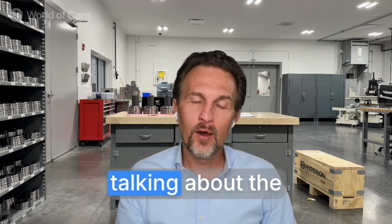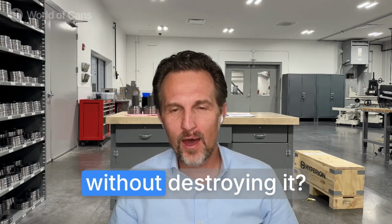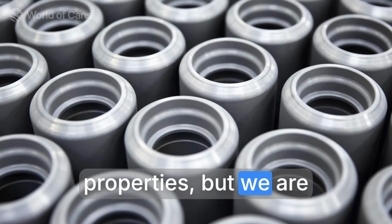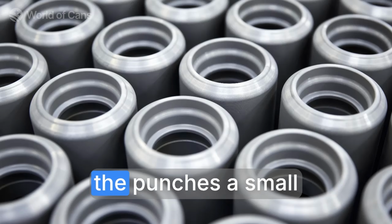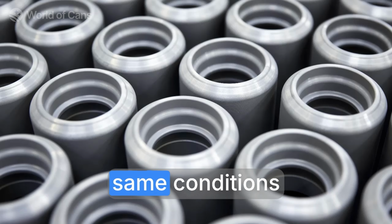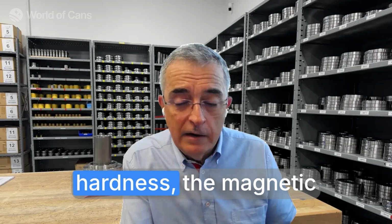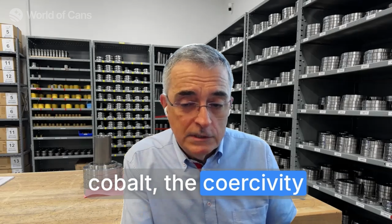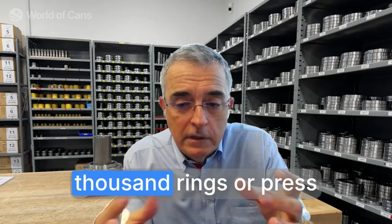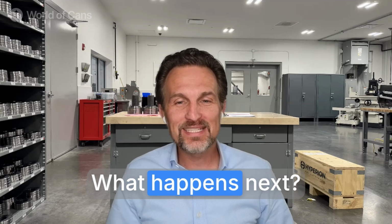When you're talking about the characteristics of the material itself, how do you test it without destroying it? For the punches, we don't destroy a punch to measure the properties, but we are sintering together with the punches a small sample made out of the same material, pressed and sintered under the same conditions in the furnace, and then we verify the density, the hardness, the magnetic cobalt, and the coercivity on this sample. And for rings, if we manufacture 1,000 rings or press a large quantity, we may destroy a ring.